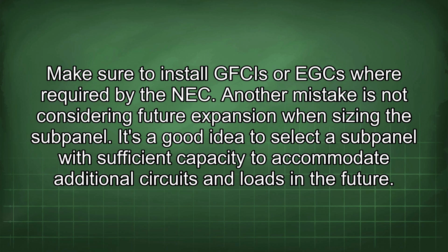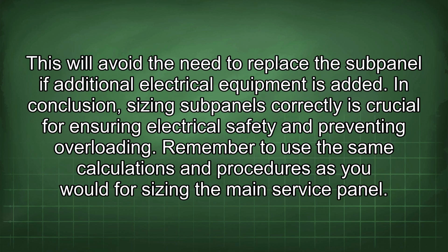Another mistake is not considering future expansion when sizing the subpanel. It's a good idea to select a subpanel with sufficient capacity to accommodate additional circuits and loads in the future. This will avoid the need to replace the subpanel if additional electrical equipment is added.